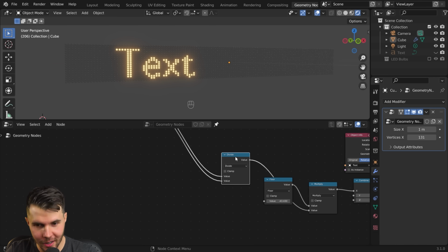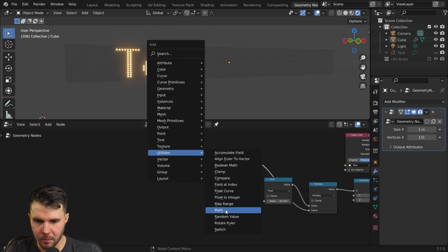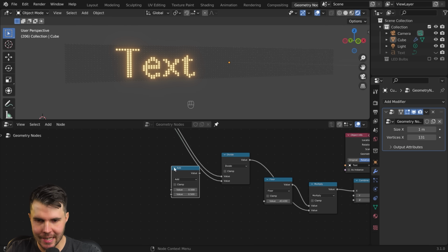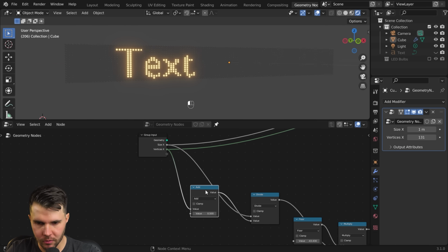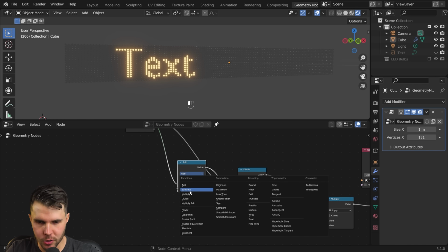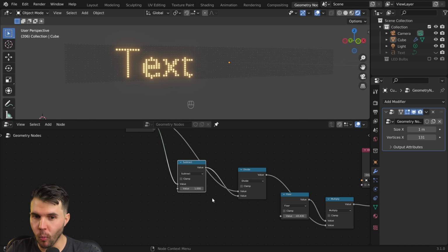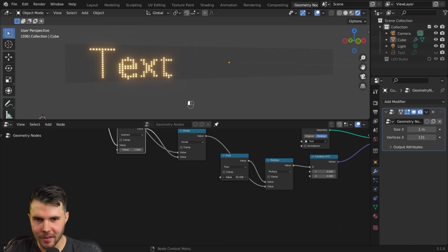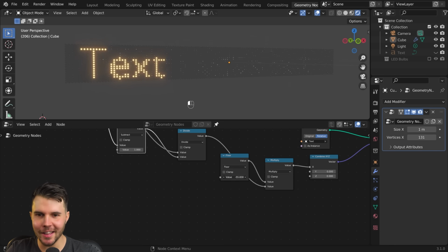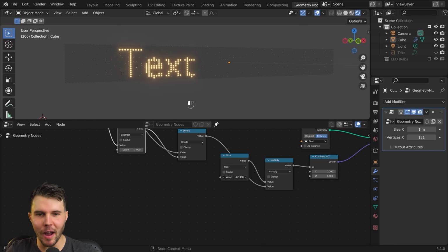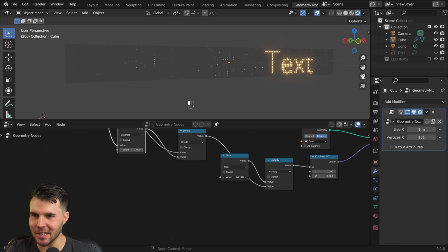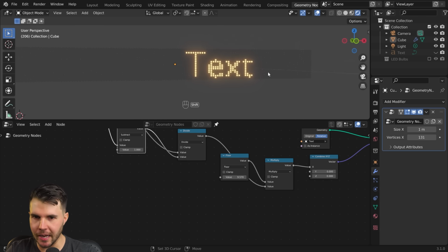So we can do another calculation. We can go Math, drop this in here, between vertices X, drop that right there, set this to Subtract, minus 1, and now this is perfect. Ta-da! And that is how you animate a ticker LED board. And you can see it's not moving, it's not stuttering, there's no vibration looking on with the text. It is perfectly aligned.